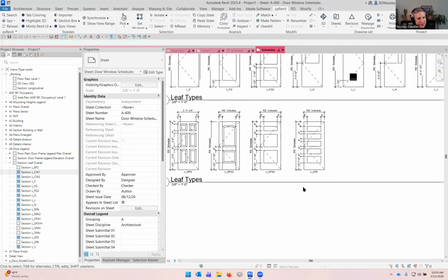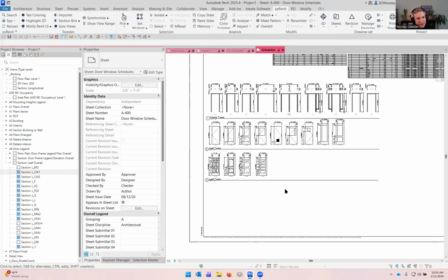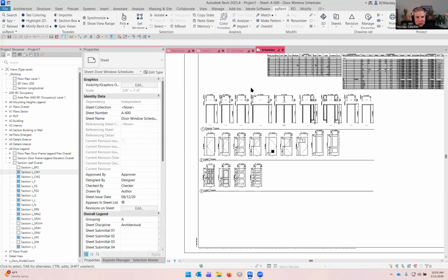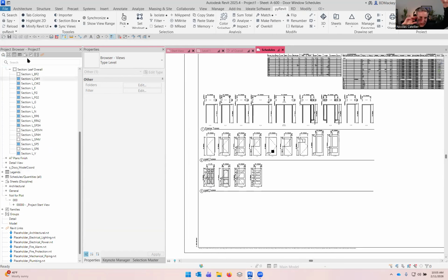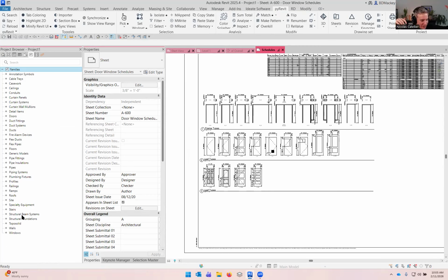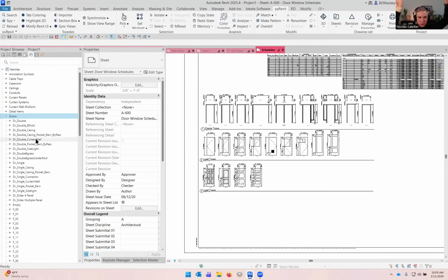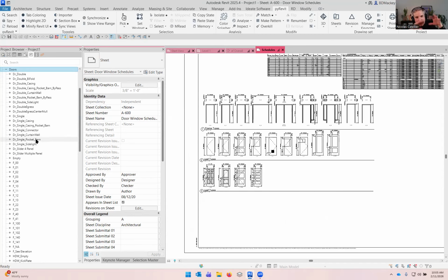So are you a subtractive template kind of guy or an additive template? Yes, I'm in between. To clarify what I'm asking, there are different schools of thought with Revit templates. Some say it should be as small as possible, and then you use automations and tools like content catalog or Reveal or Kinship to load the content and views whenever you need. Other schools of thought say you need a huge template, but when you start a project, you remove things from it. But some people can be in between, removing some stuff and adding some. So you're in that vein.